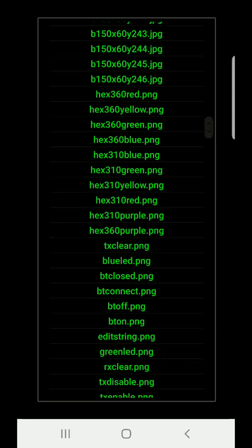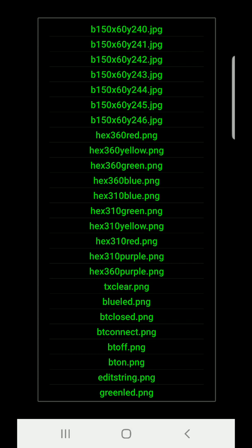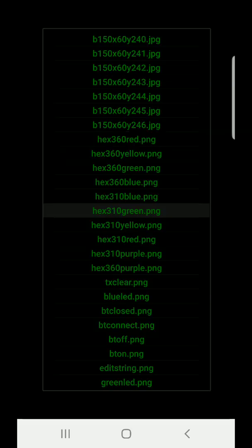The set grid options function allows you to turn the snap to grid function on or off. You can also set the snap to grid resolution as small as 5 pixels up to a large size of 70 pixels. When the snap to grid function is turned on, the graphic images will snap to a grid point based on the current pixel grid setting when performing the move function.